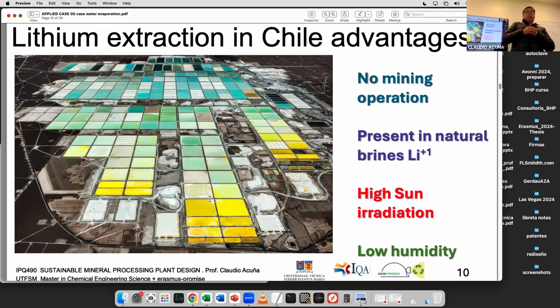But if you are in Rio de Janeiro, 90% humidity, okay? Same condition, you feel extremely hot, bloody hot. Philippines, same, bloody hot. Because with the humidity, you do not evaporate. We control the temperature by evaporation, water. Understand? Same temperature, but humidity makes the thermal sensation completely different. Okay? So we have very good conditions to evaporate.